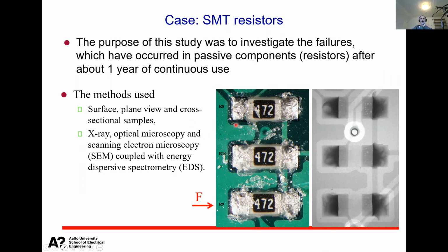And then we considered that, okay, we need to start studying the internal structure. And maybe the first guess always is that there's something wrong with the solder interconnections. So either cold soldering, so not proper solder formation, or very large voids which are also typical for these kind of components. And that's the reason that first we made some trans illumination X-ray just to check, do we see a huge amount of voids? And the answer is no.